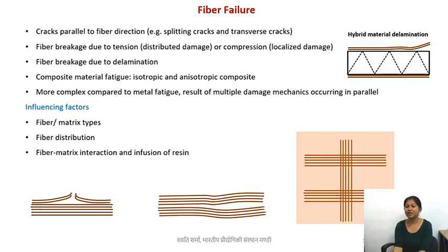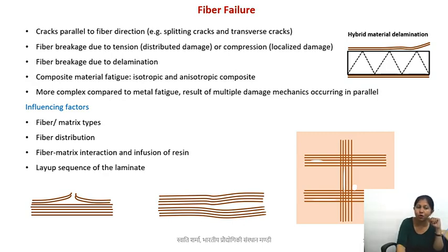The question is, is this resin uniformly distributed and wetting all the fibers, or do we have certain air bubbles, certain areas where the resin could not reach? Another issue can happen: the resin reached everywhere, but when we are curing the resin, there are certain liquid spots. There are some defects when it comes to curing. So this is also one potential problem, and that is how the resin infusion can play an important role when it comes to the strength of the overall material.